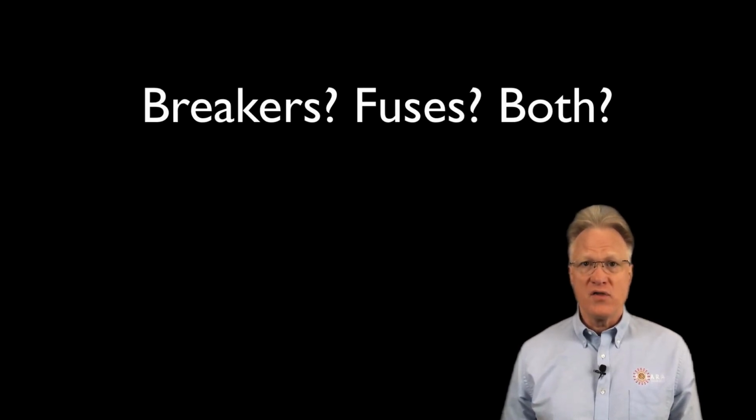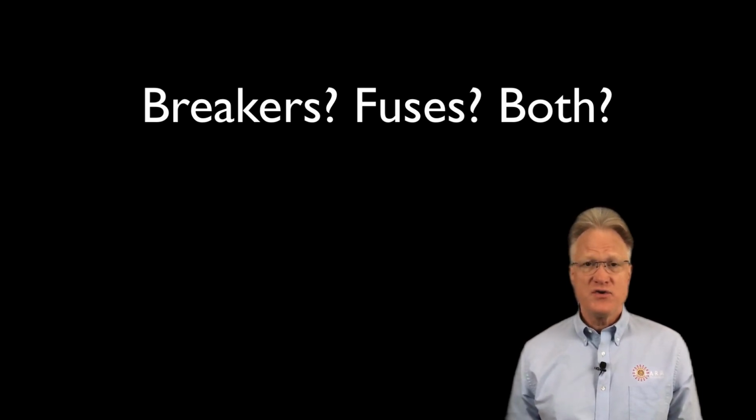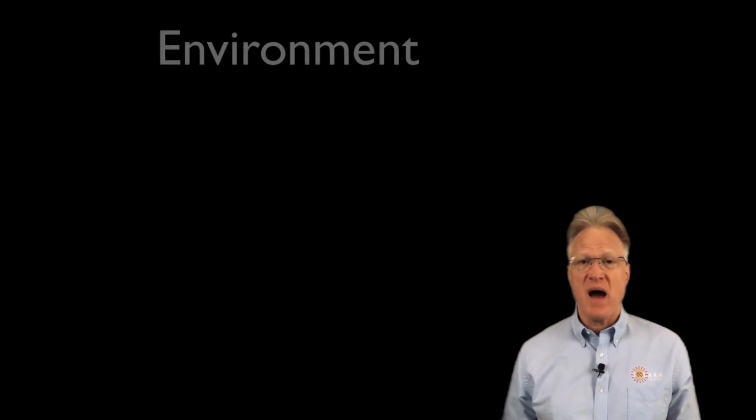What number of load circuits do you want in the distribution? If batteries are used, do you want battery distribution? And for these distributions, do you wish to use breakers, fuses, or both? And of what size?